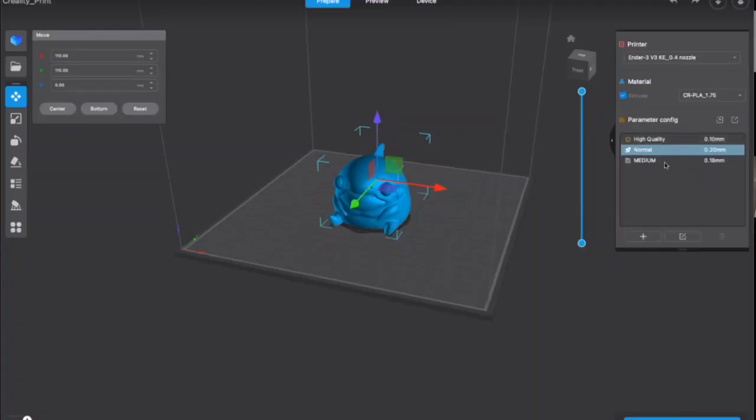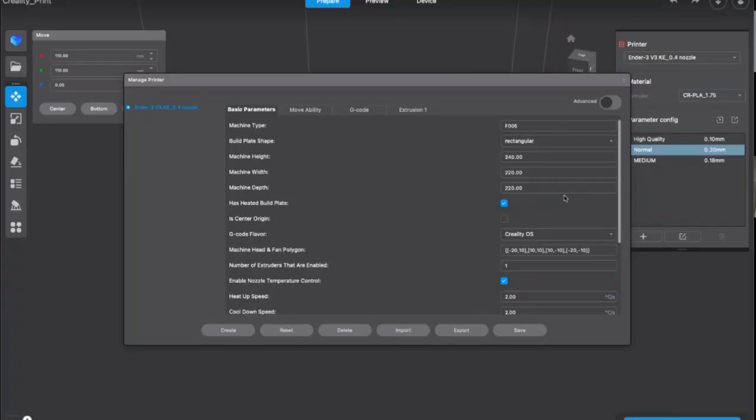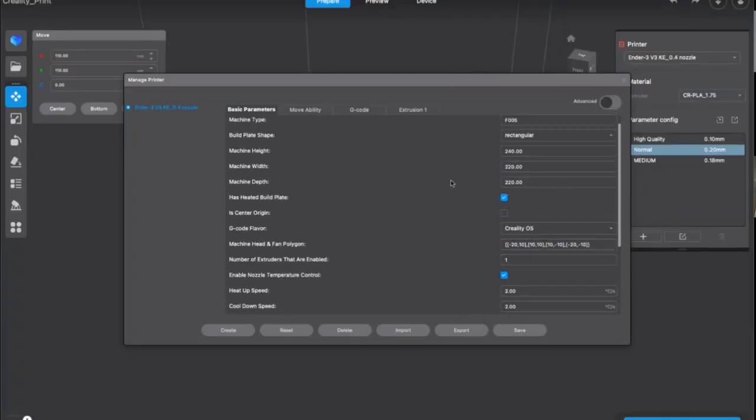After selecting that 3D printer, why we need to select it is that every 3D printer will have different dimensions. If we go for this Creality Ender 3 V3, the machine height is 240 mm, and the length and width are 220 mm. You have an idea of 3D geometry, right? As we are making 3D parts, we need to have three dimensions. In those three dimensions, consider this as height, this is x, and this is y. In this printer we can print a height of 240 mm, a length of 220 mm, and a width of 220 mm. So this was the maximum capability of this printer.